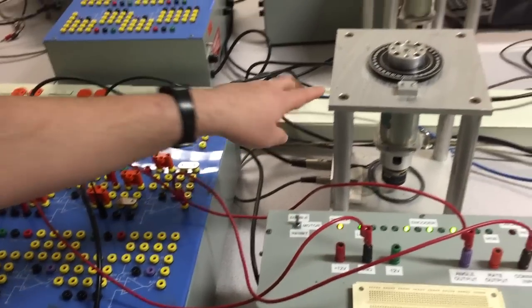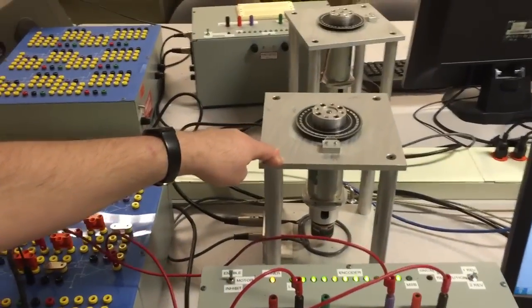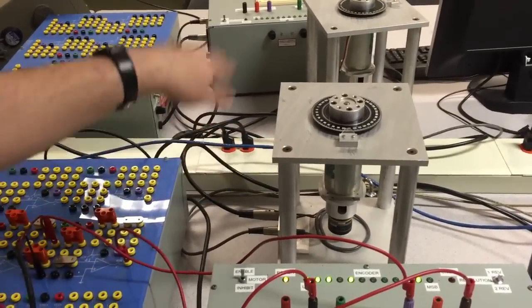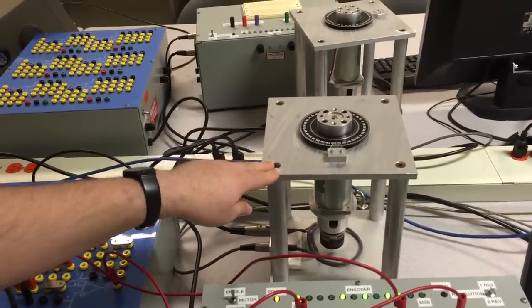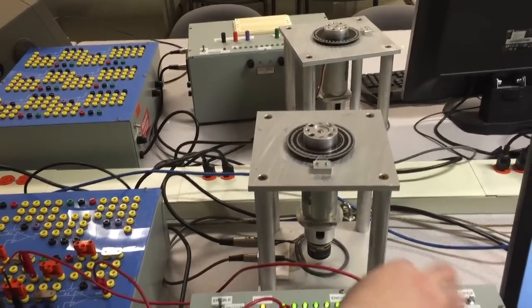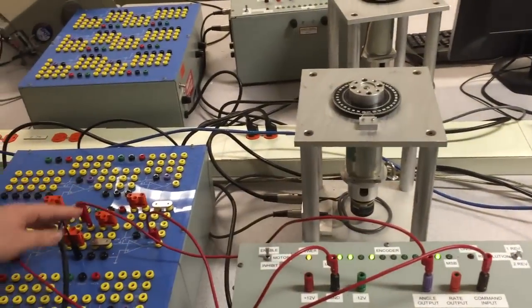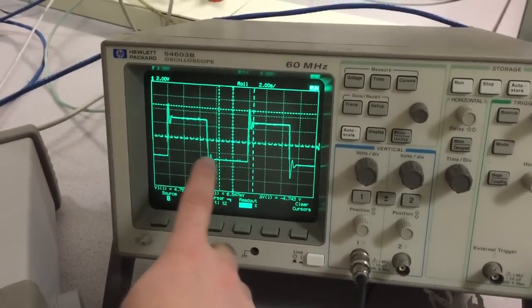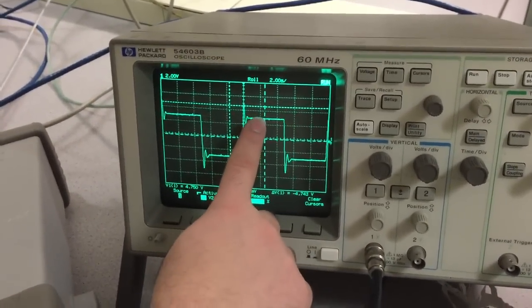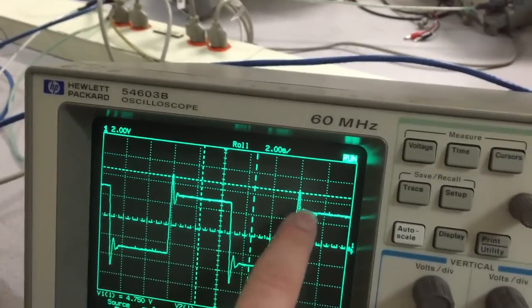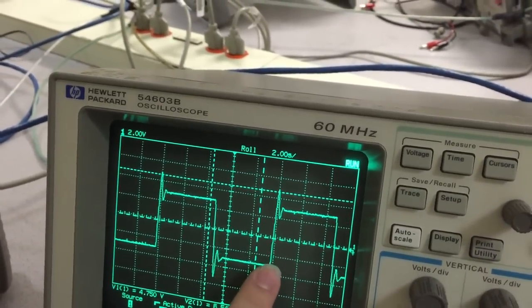If you look at the motor, you are giving it a low frequency signal. So the motor starts with a small overshoot and then stops, starts with overshoot and stops. Let's see this now. This is the angle output. We're taking it on the oscilloscope. So if we look here, we sent a square wave to the motor. If you look here, this is overshoot, then settling, overshoot, then settling, every time.